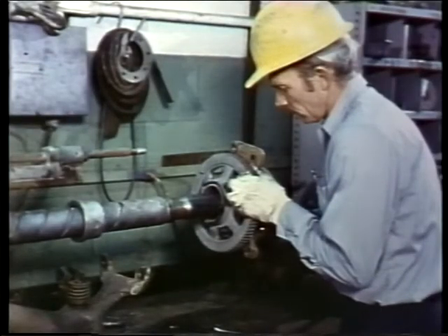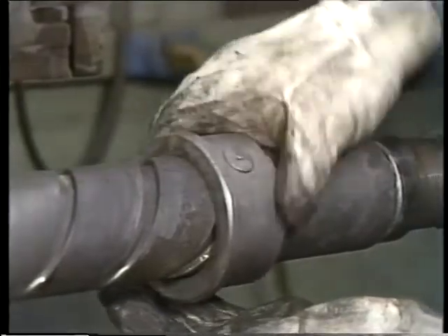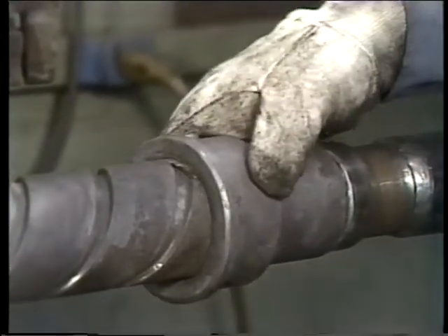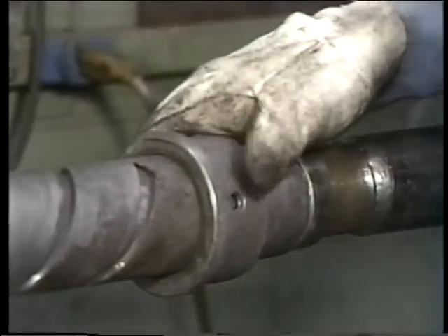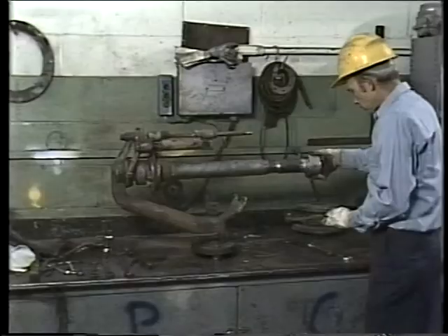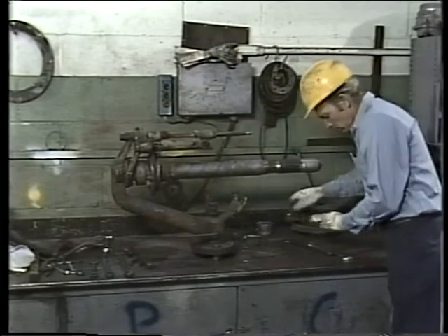The drive gear and the front mount slide over the head of the element. When the drive gear is removed, the 2 pins, called collets, that ride in the grooves in the screw tube part of the element will just drop out of the collar, and the collar will also slide off over the head of the element.